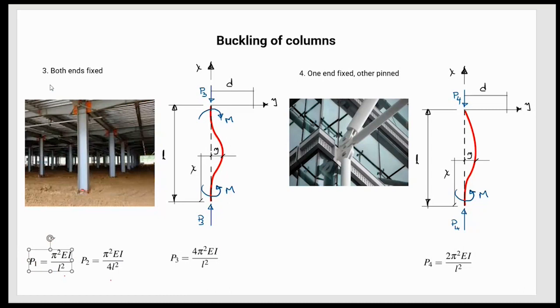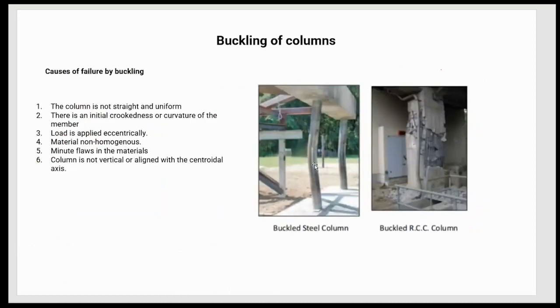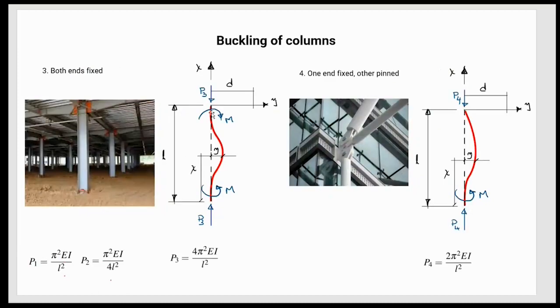And it's interesting to see, if we look at this picture again, that this is clearly a fixed condition. Of course there is deformation here, but the buckling happened mainly in the middle of the section, and that's very well aligned with the way buckling is described to happen for a fixed column. And this is also a representation of what a fixed column is.